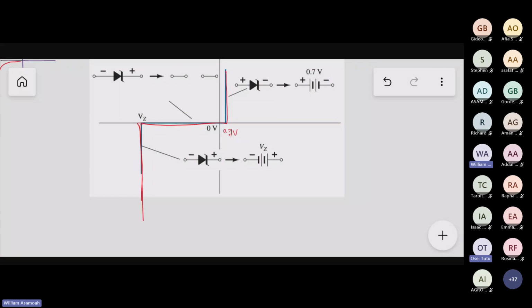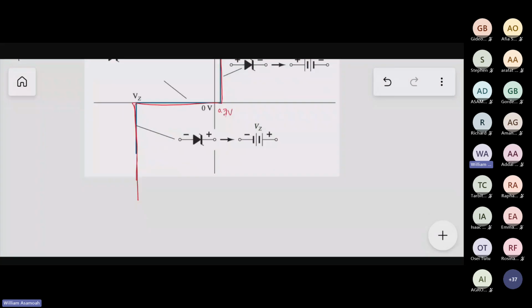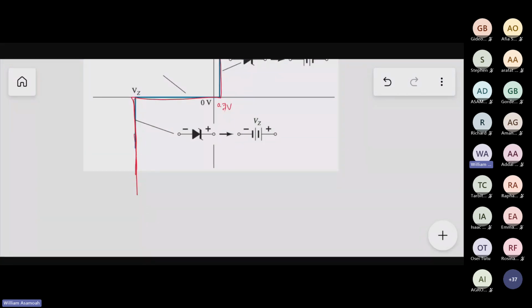We've doped it and beat it down so that regardless of how the power changes, the voltage is fixed. It keeps on going. That's how the ideal Zener diode must behave. But to be honest with you, it doesn't behave like that. To make life simple for us, we assume that even in the real world, it still behaves like a Zener diode. In fact, that is why we have special linear regulators as an alternative to the Zener diode regulators, because you don't know how it's going to behave in the real world.